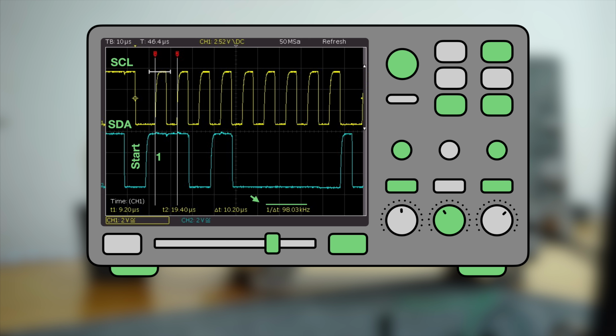In this case, this is 100 kHz, which we can tell by just looking at the time resolution here. The data bits are sent over the SDA line. The symbol 0 corresponds to a data bit of 0, and the symbol 1 corresponds to the data bit of 1, which is a high SDA line. The SDA line symbol is only valid and should only be interpreted by the slave when the SCL line is high. When SCL is low, it might still change.